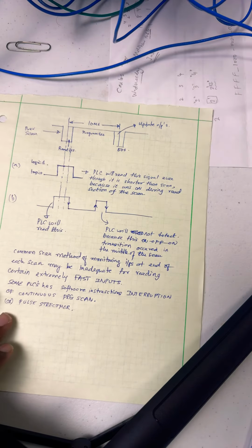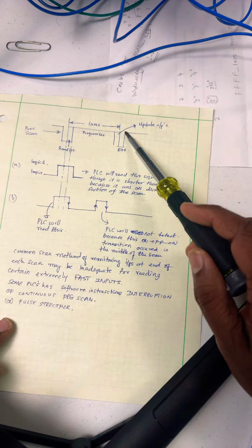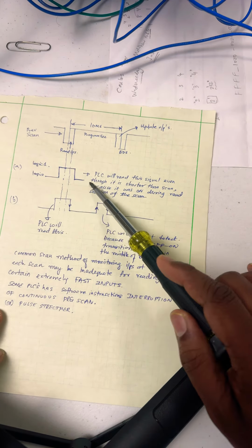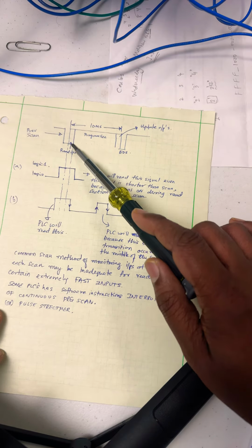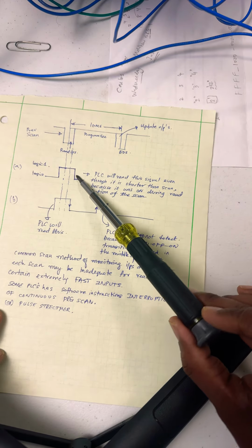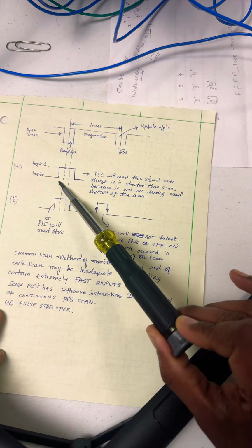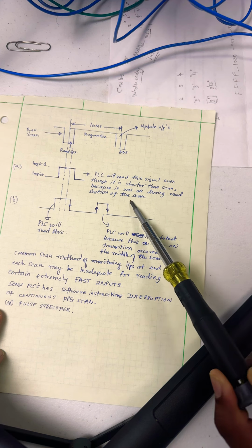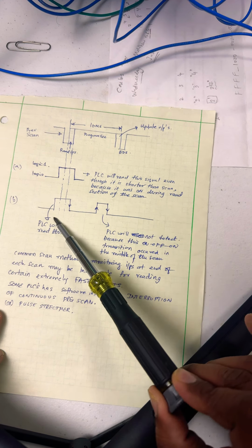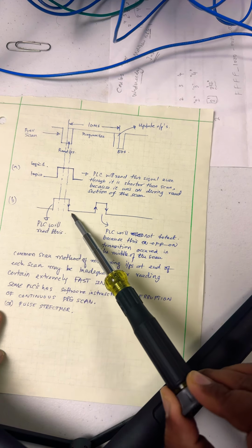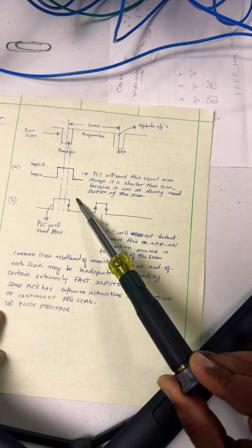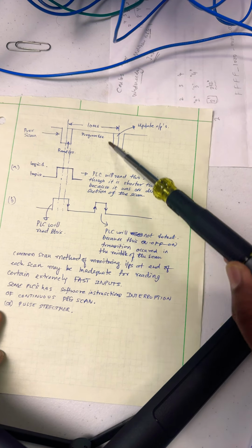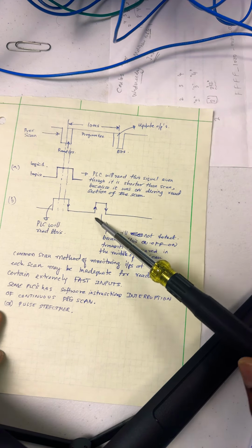So in one more similar example, 10 millisecond scan, 8 millisecond program execution, 1 millisecond input scan. In here, it will read this signal because in this window of 1 millisecond, the signal changed. So even though it is shorter than the scan, because it was on during that window, we will read it. But here, it will read this input signal, but the transition from on to off is outside of the input scanning. So the PLC will miss this.